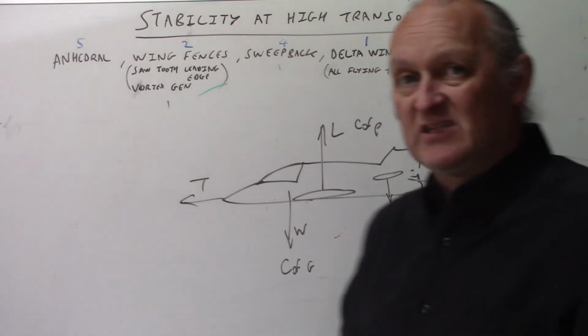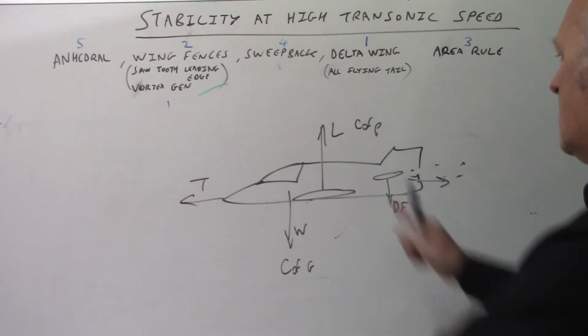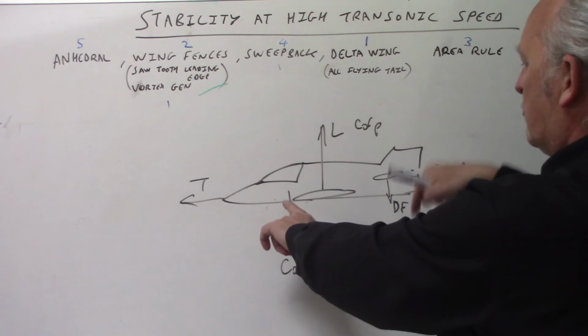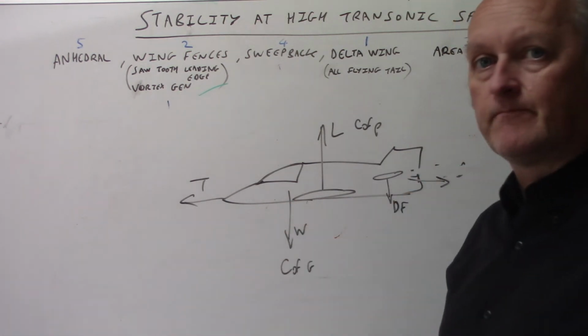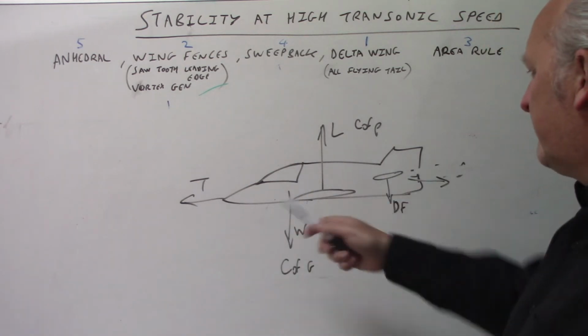That's just exactly the same lift. It's an upside down airfoil, creating lift in that direction instead of that direction. You'll have the lift lifting it up, and because it would be nose heavy, you'll have the tail pushing it down with a bit of negative angle of attack on the tail to balance that out, to make the aircraft fly in a straight line. And that's your force couple.